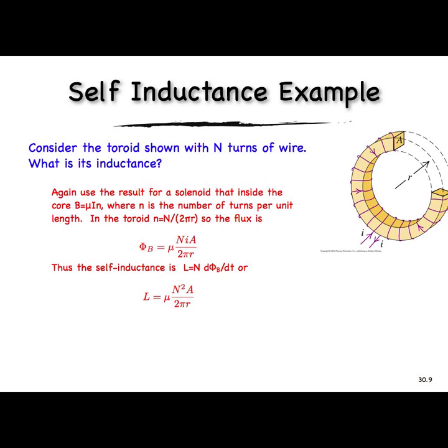And so this can be a useful effect. If you try to change the current in this coil, it produces an EMF, a voltage. So that can be a useful element to have in a circuit. We'll see in a minute why that could be useful. Perhaps a straightforward way we can understand that right now is if you try to produce a change in the current, it produces an EMF that opposes that.